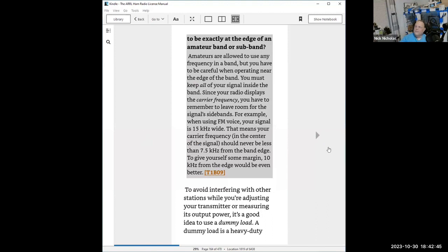Resistors come in various physical types, but they're divided into two categories. One is inductive and one is non-inductive. Heavy power resistors are generally inductive resistors. They're made from coils of wire around the insulator, but those wires are highly resistive wire. And for DC applications, they work out fine. But for AC applications, and particularly radio,